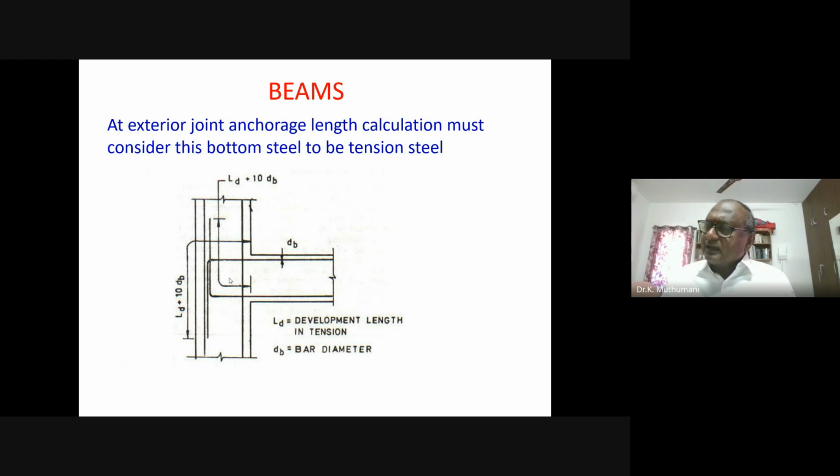Another important thing that I want to talk about is this beam, how you get anchorage. Of course, the code gives some formula, you have to follow that. There's no problem. But most of the time, it is not possible. One interesting point that happens is, suppose you finish a floor. At that point, you stop with some depth given. But at that time, you want more. This length is more than this depth. So you may ask how to insert that. So either you have to take it nicely or redesign this anchoring slightly better.